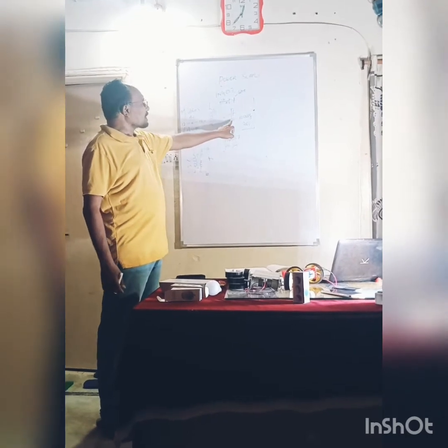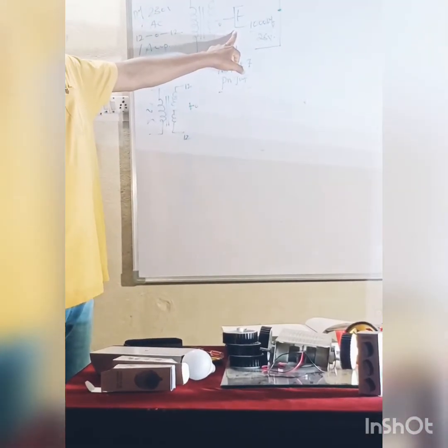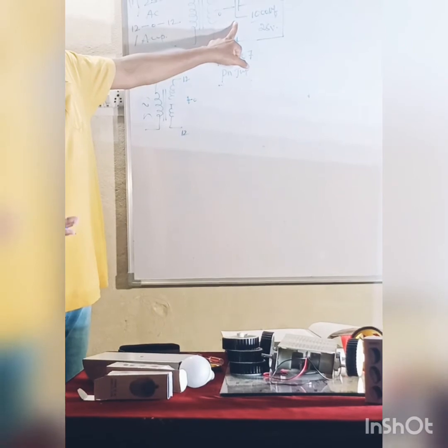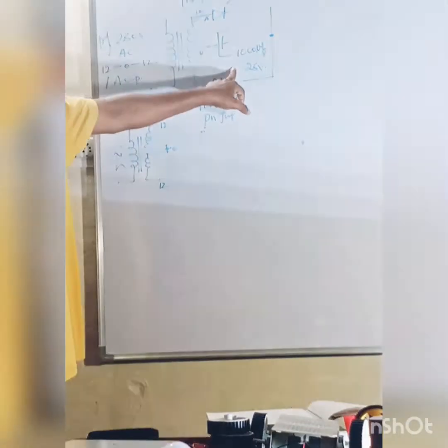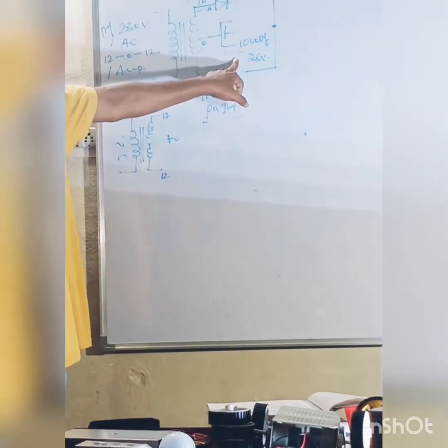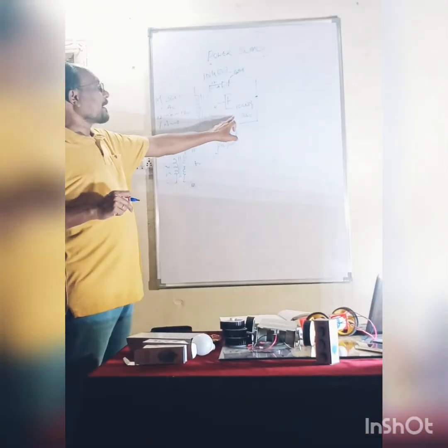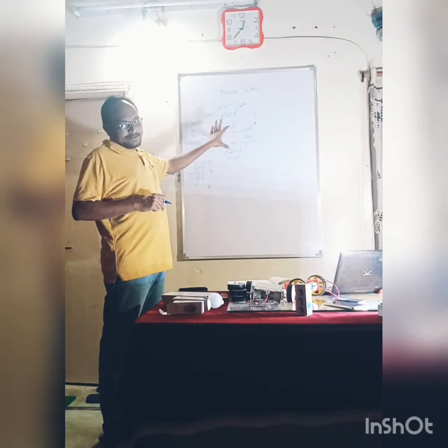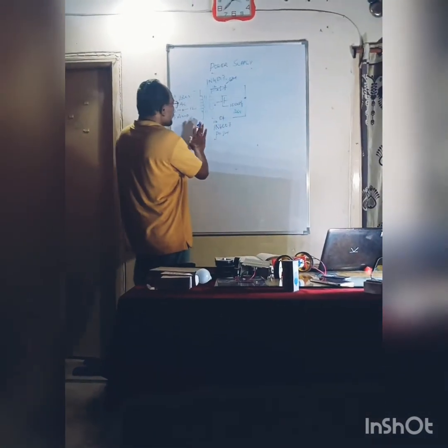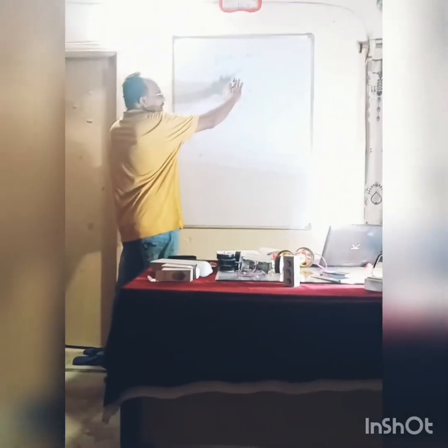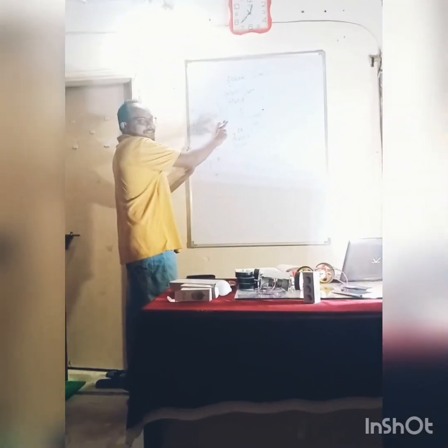When you come across capacitors, we can find 470 microfarads, 500 microfarads, 750 microfarads. I selected 1000 microfarads, so you have to answer why I selected this capacitor in this circuit. That's your assignment. Now we finished step down, rectification and filter.